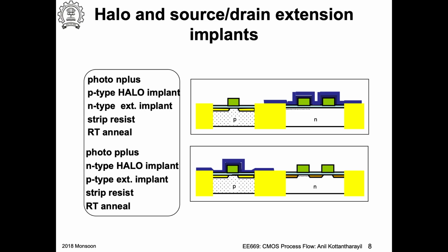Now in the next quadrant, the next half of the wafer, what you're doing is rotating the beam towards the right, from the vertical, and then you do again a boron implant. So you will implant some boron under the gate.